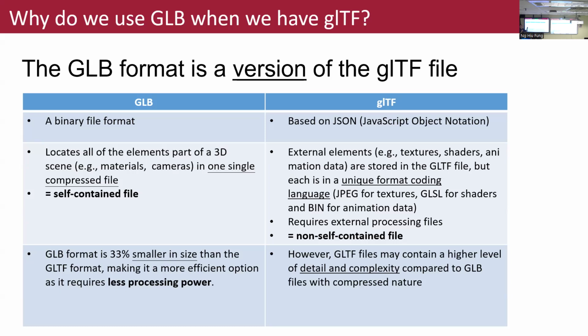If something is one time, that means it's launched once, it's ready to run, and you will not modify it by a human anymore, use GLB. GLB is read by the computer, and the computer can run binary files faster. If it's one time and you do not modify it again, GLB.